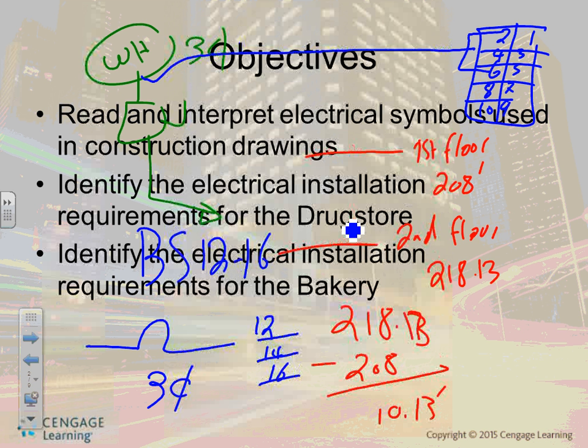When the power comes back, the gen will wait for 15 minutes. Typically, there's a delay. So the power comes back, and for 15 minutes you monitor the power. Is it stable? 1 minute, 2 minutes, count to 15 minutes. After 15 minutes, yeah, it's stable, go back to the normal rate. They don't shift you immediately. It's smart because when you have a storm, sometimes power comes and goes immediately, right? So you don't want the generator turning on and off all the time.